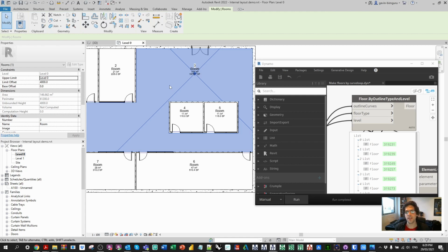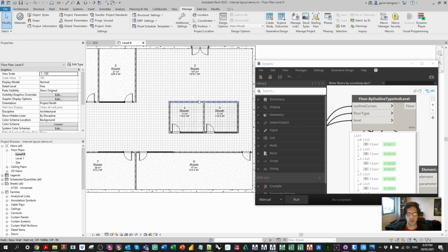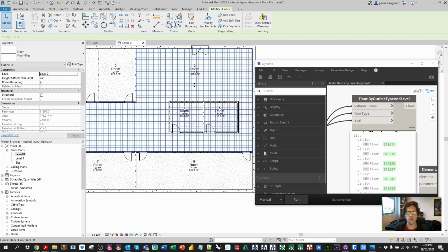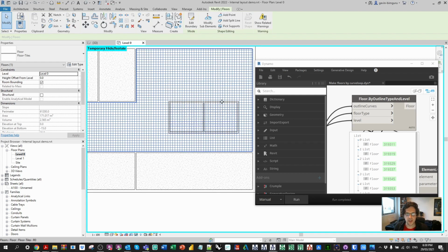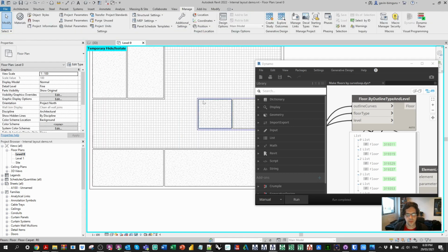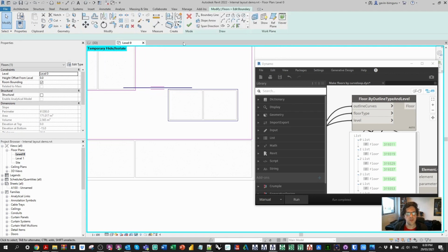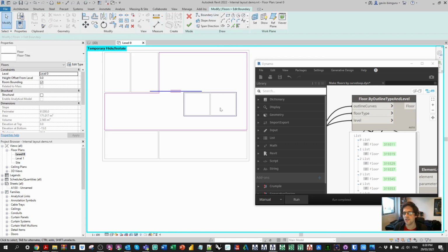So in this case, we're going to be taking the room finish boundaries and trying to generate floors that actually contain internalized curves as well. If I run this current script, notice that if I generate this tile floor with two outlines, it's going to generate the overall floor, and it's also going to generate the internalized floor component as well, which really isn't what we want. We really want it to exclude that element, and we want it to cut out this element from the insides. We really want it to have this internalized sketch boundary, which in this case it does not.